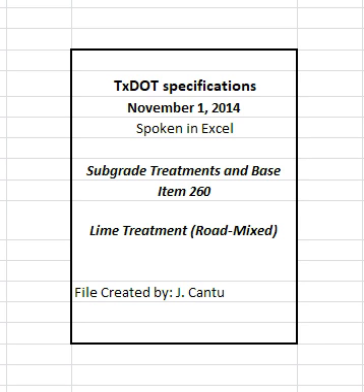2.3 Flexible base. Unless otherwise shown on the plans, furnish base material that meets the requirements of item 247, flexible base, for the type and grade shown on the plans, before the addition of lime. 2.4 Water. Furnish water free of industrial wastes and other objectionable material. 2.5 Asphalt. When asphalt or emulsion is permitted for curing purposes, furnish materials that meet the requirements of item 300, asphalts, oils, and emulsions, as shown on the plans or as directed.